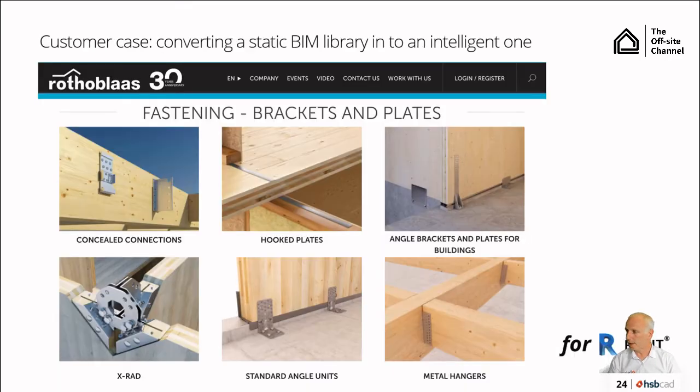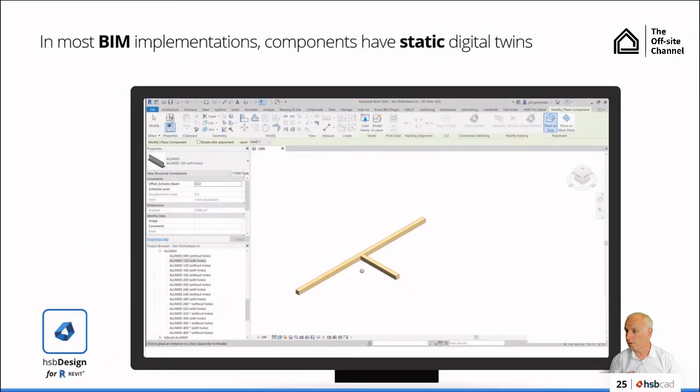Contrary to Revit, we also have partners. For example, Rotoblast, one of the bigger tooling and fastening customers of ours, have put their complete library inside Revit today. What's very important, what I'm about to explain next, is that one can in the Revit space create their own family metal part. But the issue they will have is that upon placing that metal part, if there's any editing of the beam, such as moving the beam afterward, the metal plate is not attached to the beam.